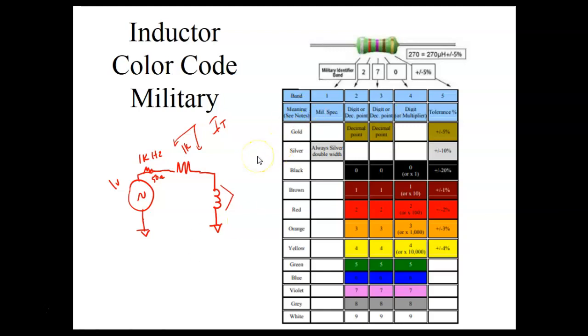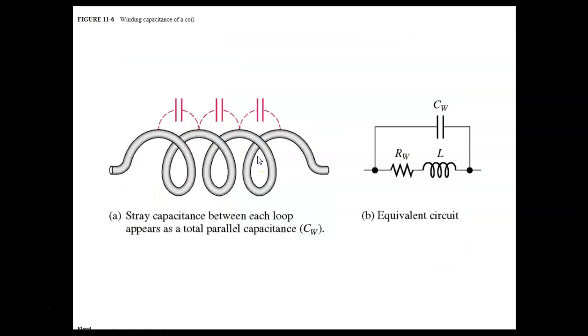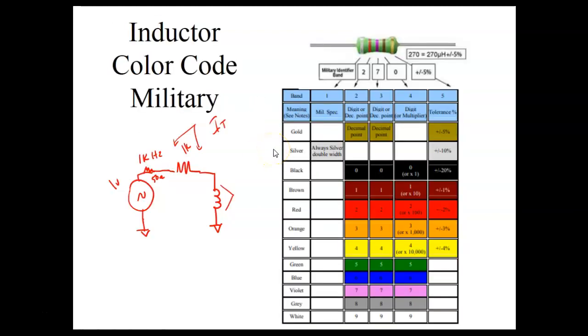So I keep a box of those things at the house all the time. They're cheap too. For a box, you go down to Lowe's and buy a whole box. But make sure you buy the right ones. Like these are 20 amp plugs. They got a little notch on the side, and these should have 12 gauge wire runs. So don't go out and buy a 20 amp plug so a 20 amp plug cord will fit in there.